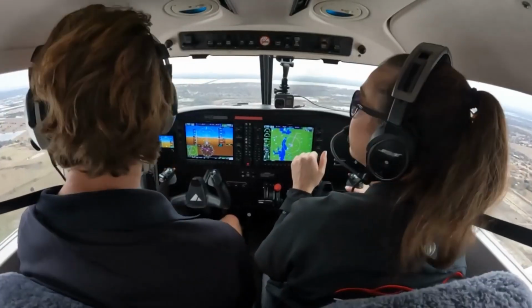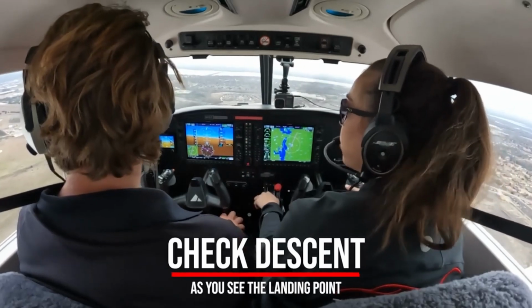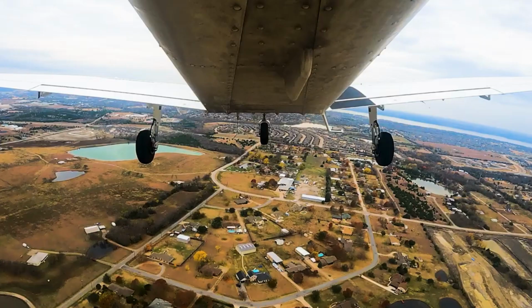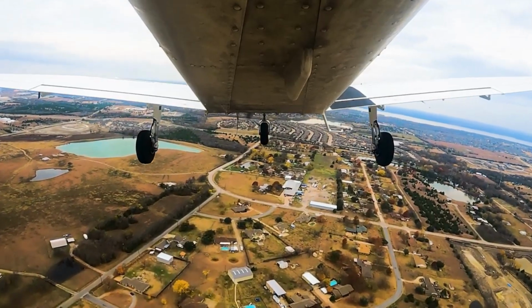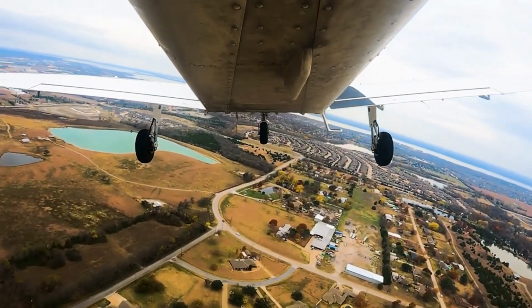Conversely, if the airspeed is below best glide, then pitching down will increase the airspeed and shallow the descent angle, while pitching up will reduce the airspeed and will greatly steepen the descent angle. If the airspeed is too high, the pilot should raise the nose, and when the airspeed is too low, lower the nose.